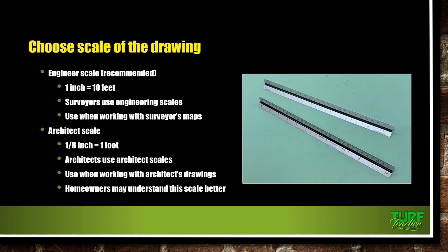But again, choose the scale of the drawing. Engineer: 1 inch equals 10. Surveyors use engineering scales. Use it when working with the surveyor maps. Architect scale: 1/8 inch equals foot, 1/4 inch equals foot. Architects use the architect scale. It's used when working with architectural drawings. Homeowners may understand this scale a little bit better because it's kind of familiar with the tape measure.